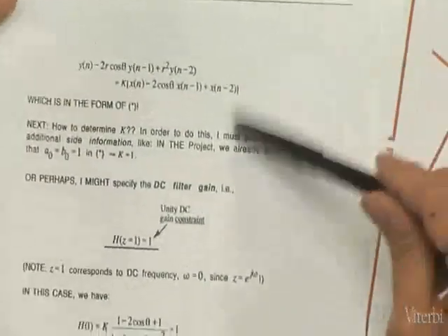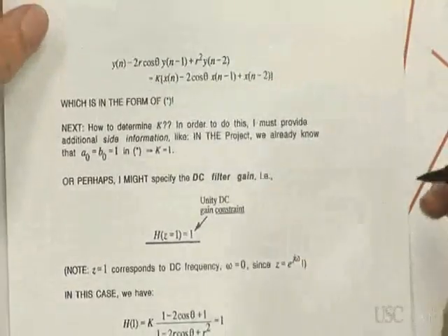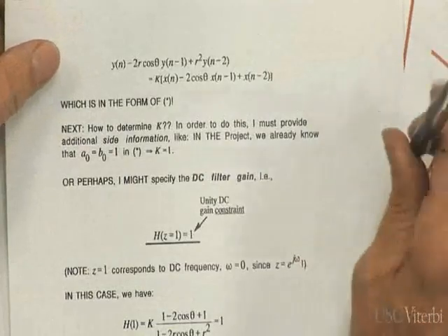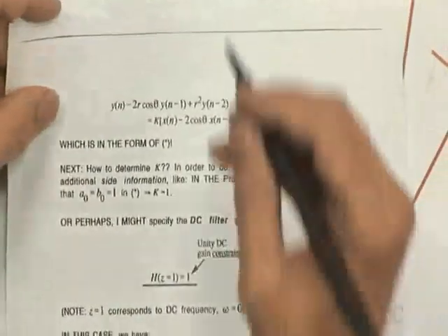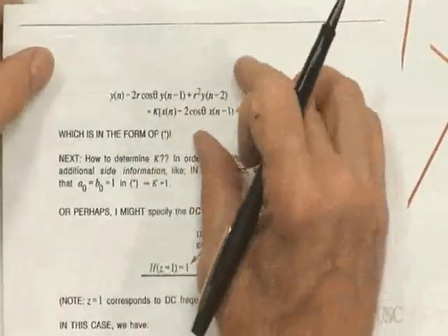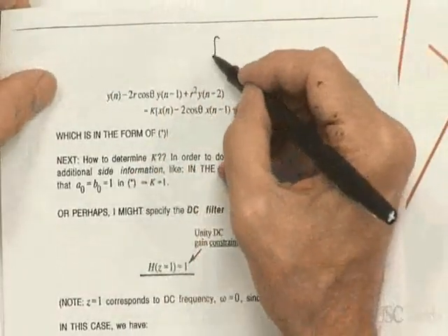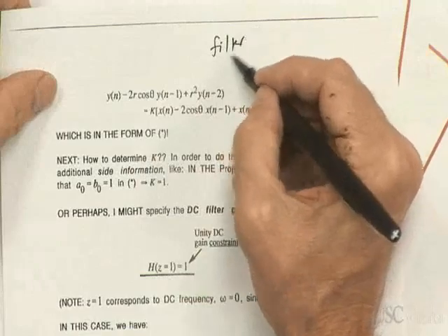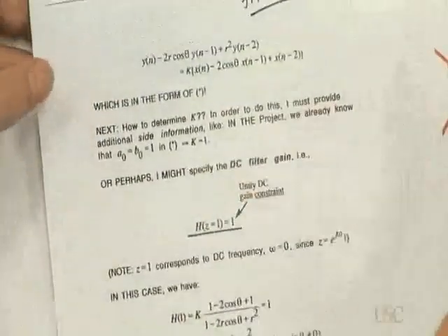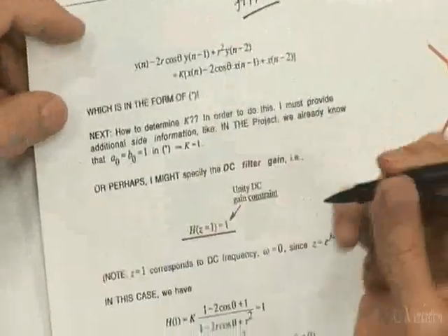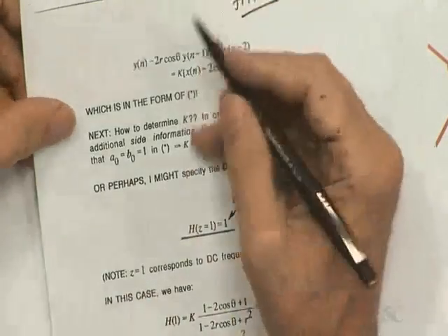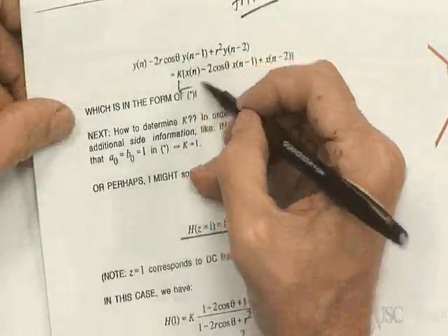And my difference equation looks like this. It's a second order difference equation. Okay? And that is how you would implement the filter. In MATLAB, using this form, you could use the MATLAB filter function. Or if you're programming an FPGA or whatever, this would be the form you use to actually generate samples.